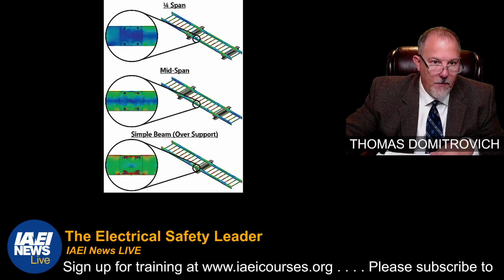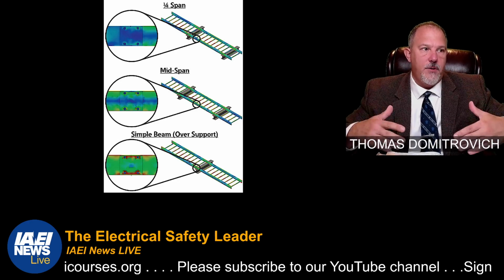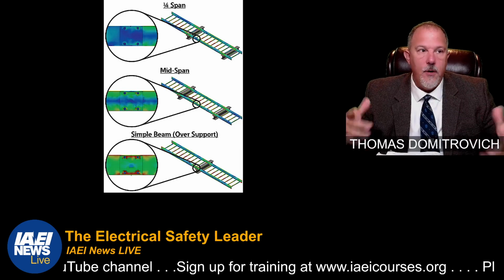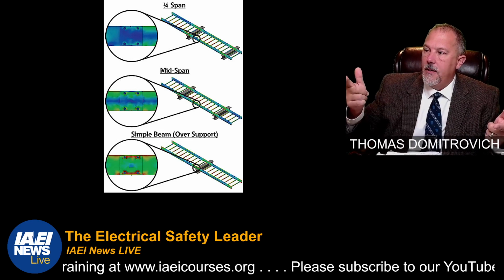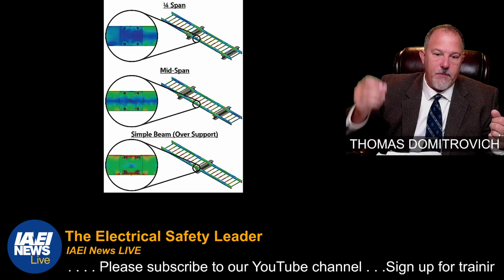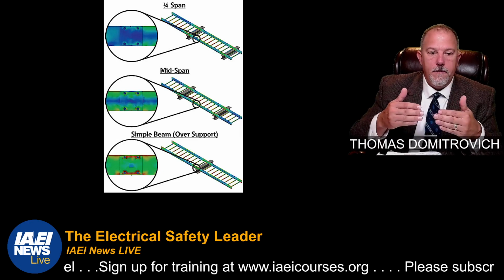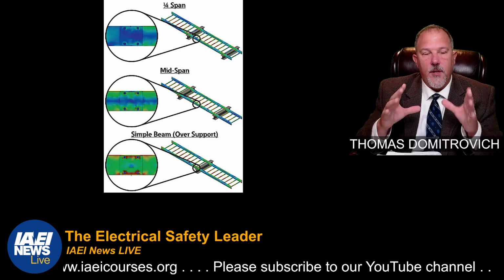Now, you've got to think about how much weight is going to be on the cable tray, obviously. For example, what we're showing here is when you're doing splices, the proper method for splicing and the proper way to connect two cable trays together is very important. So a splice plate, that plate that you see in between there, is what's going to bring two cable trays together.